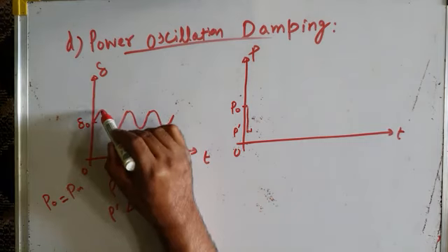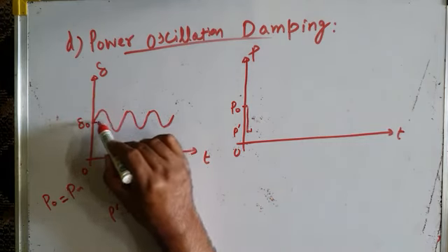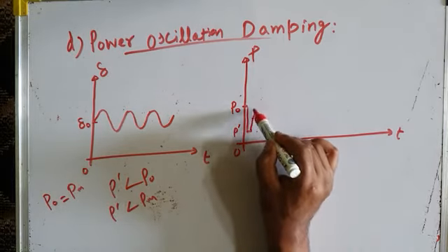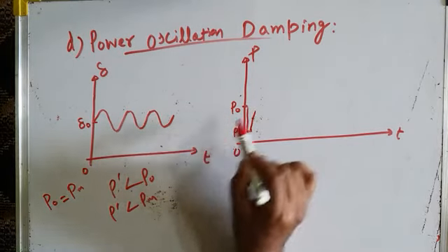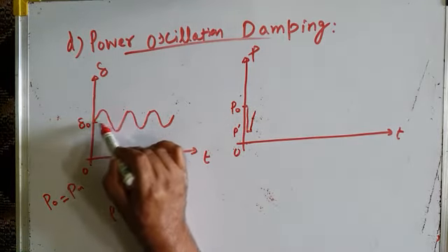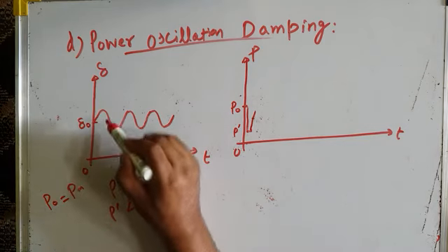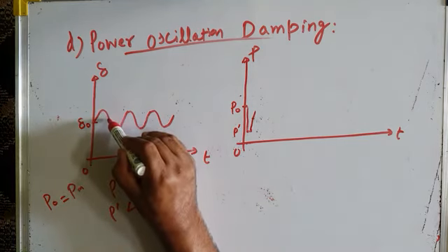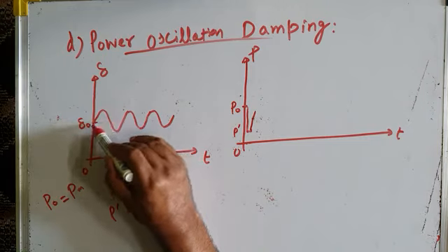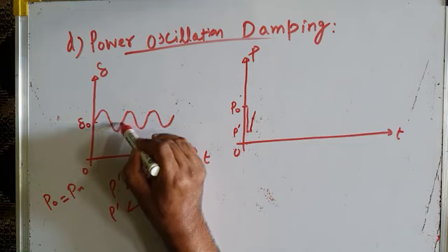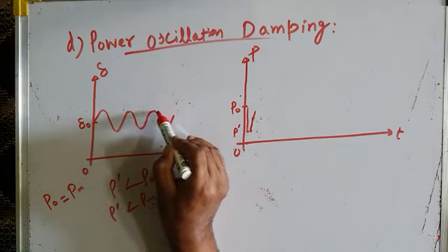It reaches some higher value and then it should come back and settle, because when this disturbance settles, it should come back and transmit power P naught, and this should also come back and settle at delta naught, but that does not happen. If your system is uncompensated or undamped, then there will be permanent oscillations. The transmission angle will come back to delta naught, which is the steady state value, and then it will become less than this, and then it will again increase, decrease, again increase, decrease.